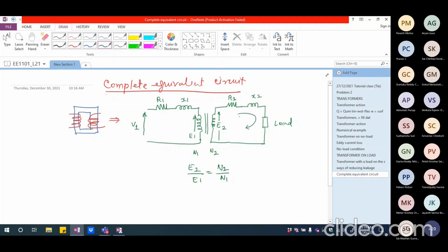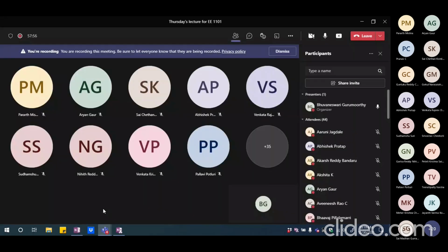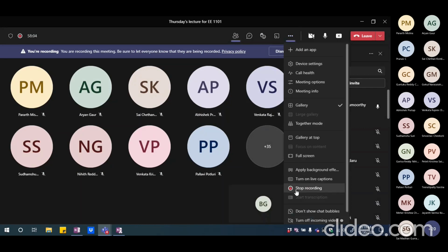So this is the load current which is taken by the transformer secondary side, and that is being supplied by the secondary side of the transformer, and you are going to have that reflected on the primary side, and I may call that I1, which is actually I1 dash plus IM. Okay, so we will expand upon this further in the next class regarding the equivalent circuit of the transformer, and as we go along, we will take all the non-ideality